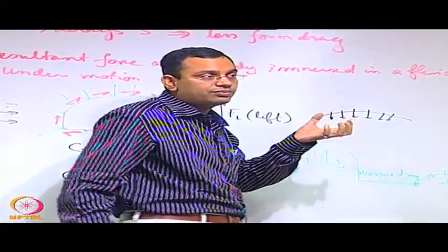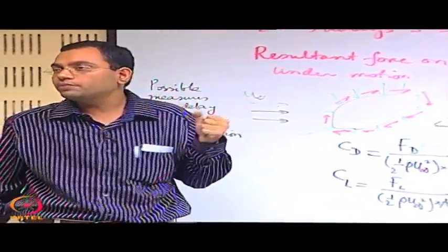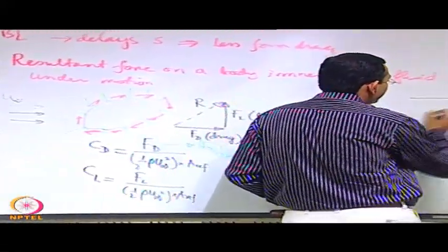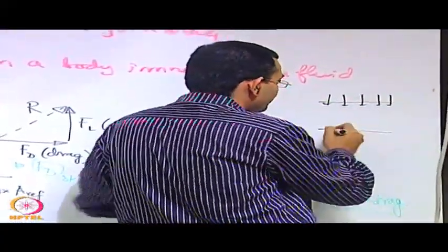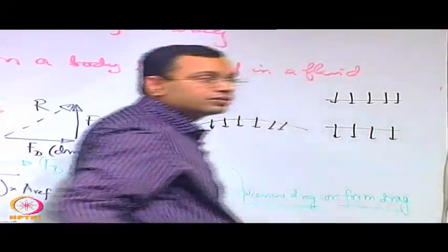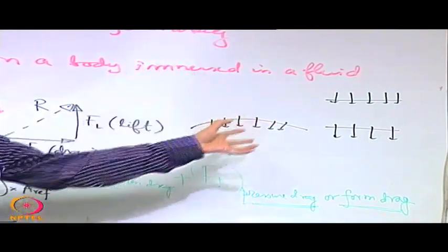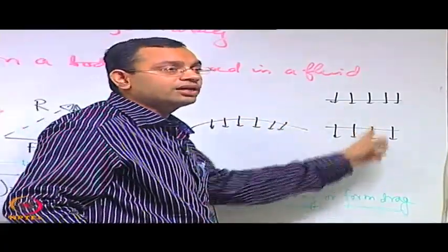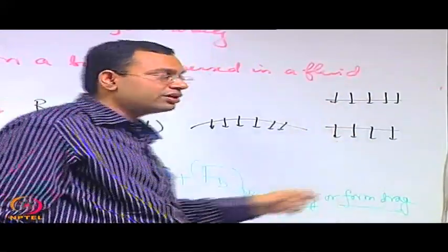We have seen that one of the reasons for boundary layer separation is that the fluid in the boundary layer does not have sufficient momentum to overcome the adverse pressure gradient. In the previous class we looked at one example where you put some fluid through holes from the top and suck it from the bottom. This is one way to create greater momentum in the boundary layer. You could also do it the other way, injecting fluid into the boundary layer. Increasing the momentum does not depend on whether it is upwards or downwards. So you might have boundary layer injection.